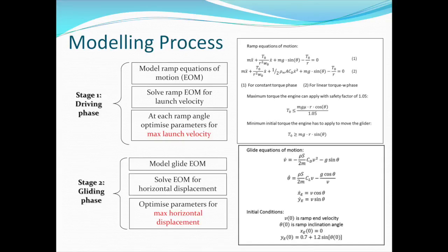Glide equations are then solved for the trajectory. Each angle along with its maximum velocity is used as the initial condition, and the angle for furthest glide is identified. Assumptions include decoupling of lateral states, constant small angle of attack, and longitudinal static stability.